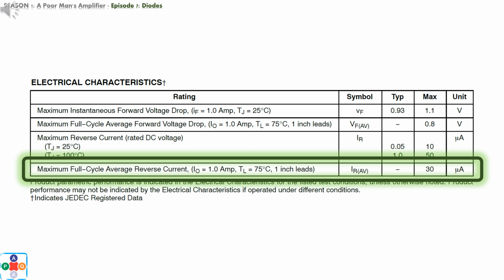In this scenario, the above-mentioned reverse current parameter does not mean that current is flowing in the reverse direction, from the negative to the positive terminal of the power source. The term reverse addresses the reversed orientation of the diode itself. Simply put, in this context, reverse means that we flipped the diode and connected it the wrong way around. This is just another in myriads of poor naming examples used in the theory of electronic circuits.